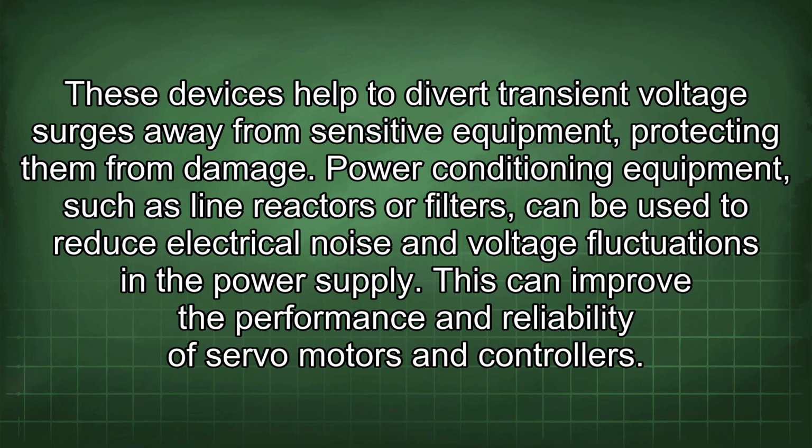Power conditioning equipment, such as line reactors or filters, can be used to reduce electrical noise and voltage fluctuations in the power supply. This can improve the performance and reliability of servo motors and controllers.